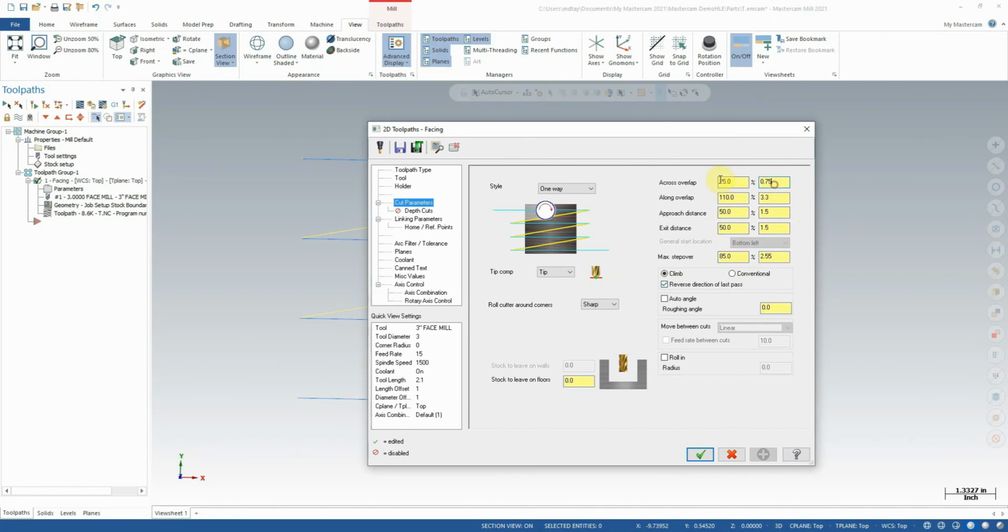However, by changing this value, I've learned what the problem is with our toolpath. The problem is that it's trying to overlap the edges of our part by 3/4 of an inch, and the max we're allowing our cutter to step over is 2.55 inches total, which means overall we're only cutting a total of 5 inches and 100 thou. 5 inches plus 0.75 extra is going to be 5.75, and we're only cutting 5.1 total. So this is where our inconsistency is coming from. It's trying to overlap the edges of the part for us, but that's actually causing us more harm than help.